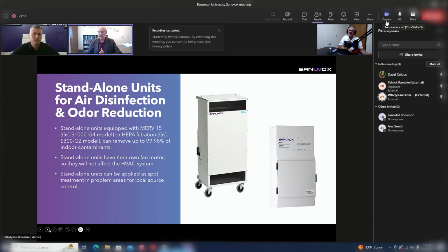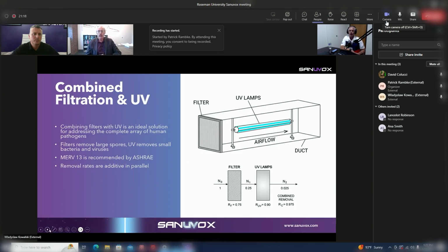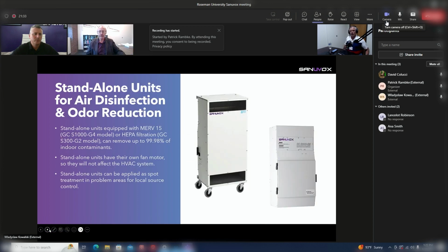What size pleat is that? Is that like a 3-inch, 1-inch? Do you know on that MERV 13? Are they requiring a specific one? MERV 13 filters, I think they're about 1 inch thick typically. And the pleats, well, I don't know how many pleats, but there's probably a couple dozen across an 18-inch width of the typical filter. So pretty much a standard 1-inch pleat would work depending on the size of your duct, right? So you can put in a 20 by 20 or whatever. They're pretty standard, and they're widely available.